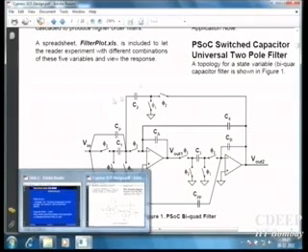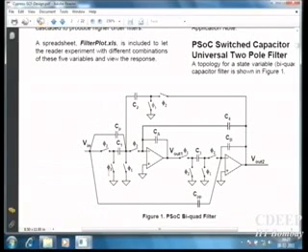Now you know the configurations. Let's look at this architecture. I will draw the corresponding analog version of this continuous time. So see, here you can see, first of all, you see switch sharing, the same thing we did, right, between C2 and CP. So one capacitor is already there, the same thing we had in first order. Here you will see emulation of one resistor, right, using backward Euler. Here is that integrator, which has a constant capacitor CA.